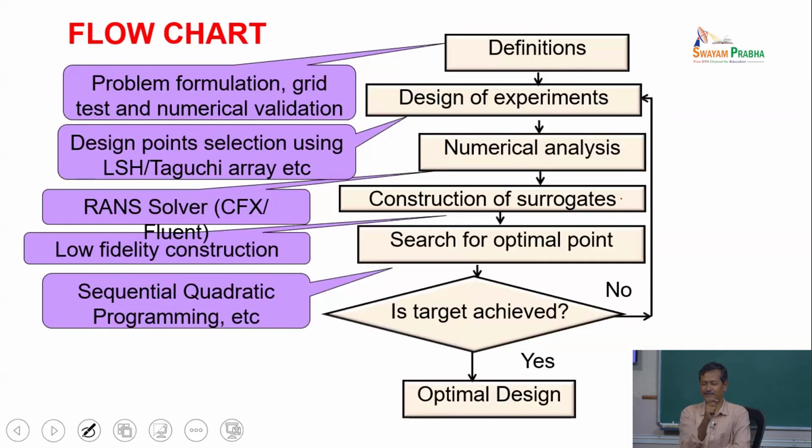Let us say design 1 you simulated, you got efficiency 70%, simulation 2 you got 65%, another 75%, another 80%. So, you cannot say, sir, 80% that one is the better one, maybe 81% is better, but your design does not contain that 81%, right, because 1% efficiency also will be good, especially in gas turbine applications and those applications where technology is very mature, a 1% efficiency increase is very high.